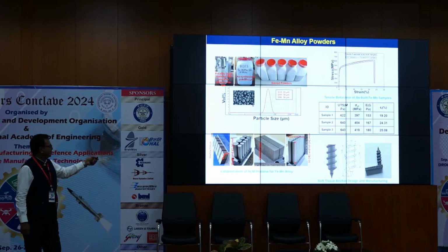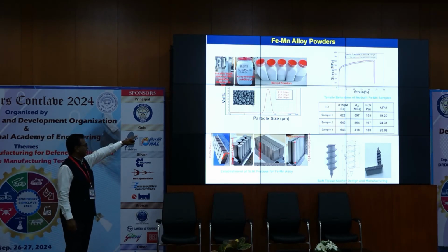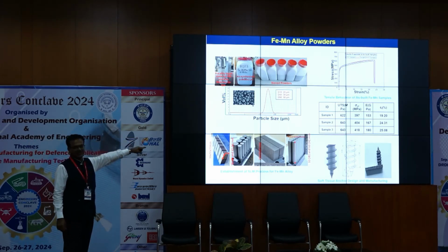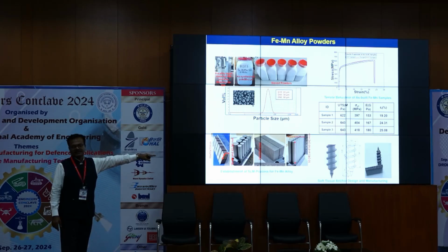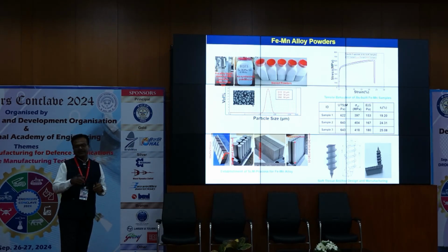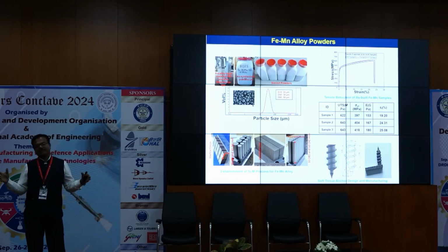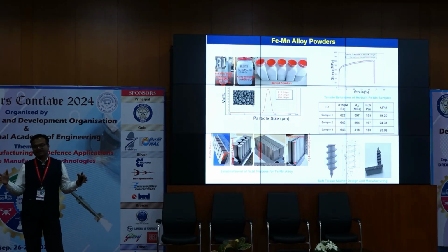Typically, we look at the particle size, we screen it, and the yield. For AM SLM, we want a size range of around 25 to 58 microns, with the peak around 40 microns. That's the powder you get. But you also end up with higher coarse fractions, so you have to sieve it. Our experience is that we get around 60% of this fraction that is suitable for AM.